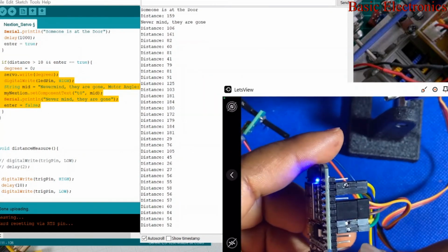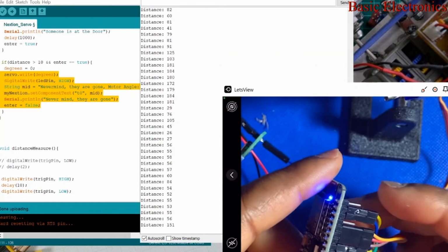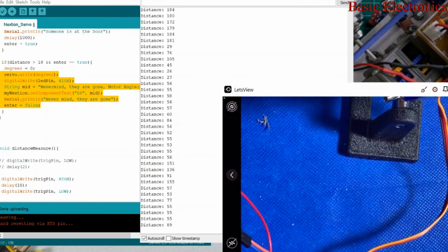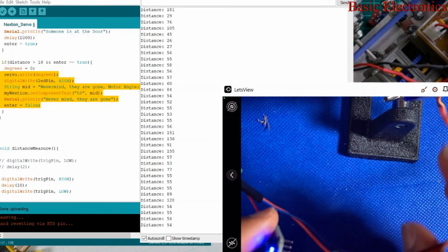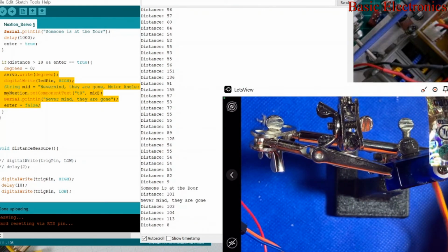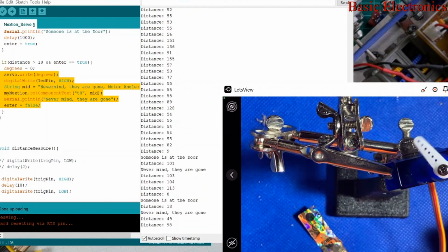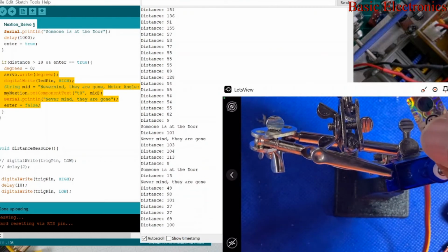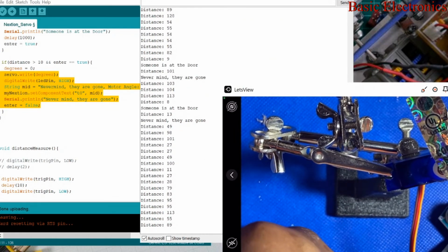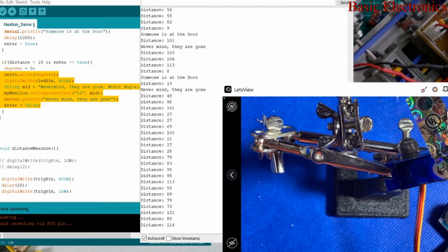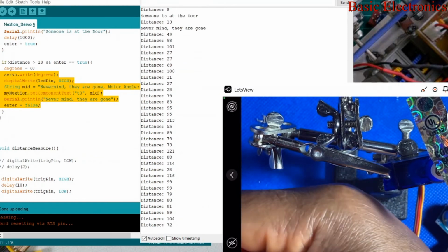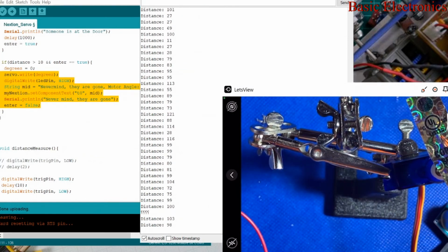So we have 7 wires from the NodeMCU, the 2 for the signal that go to the Nextion editor, and then the 3 that go to the servo motor, right here, and then the other two that go to the sensor we're using here. And then for the power, we took everything from the power port, if you will. Okay, so I'm gonna plug this back in.